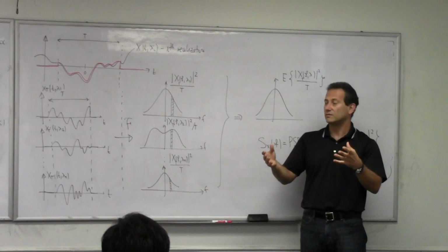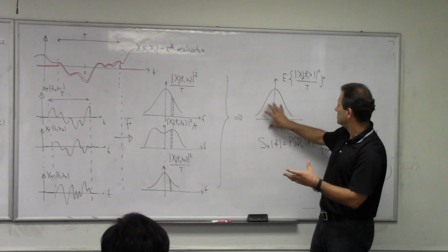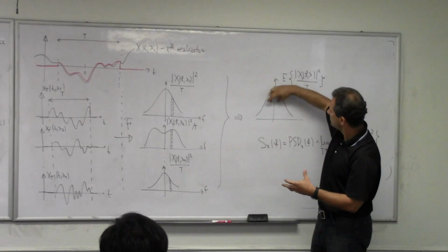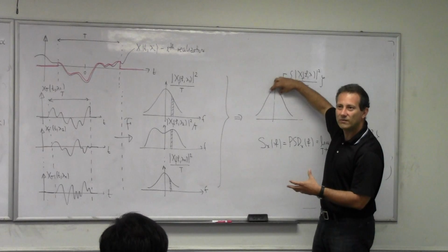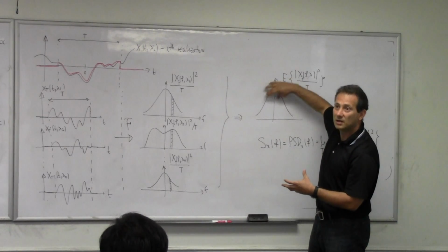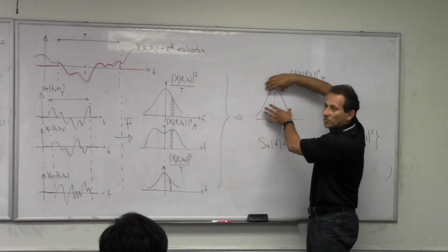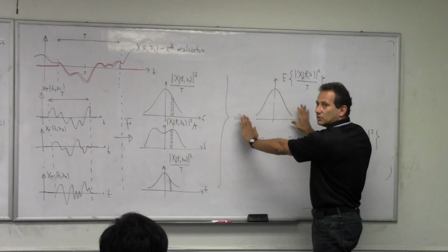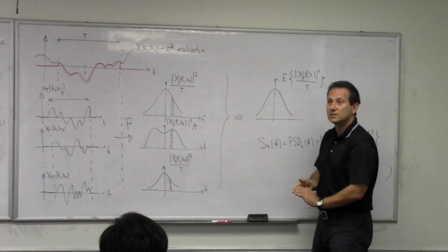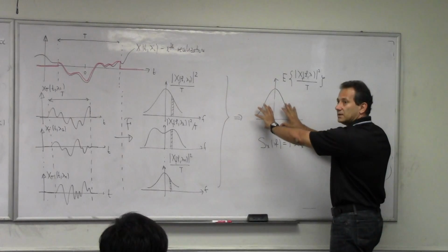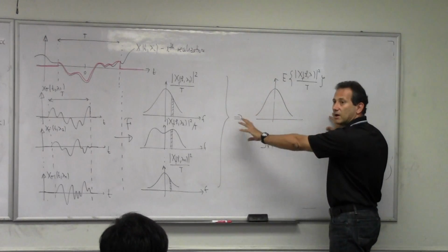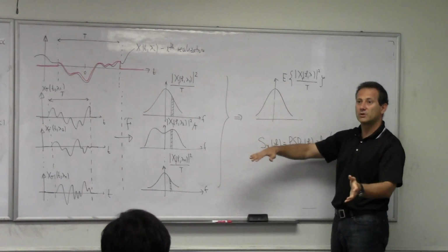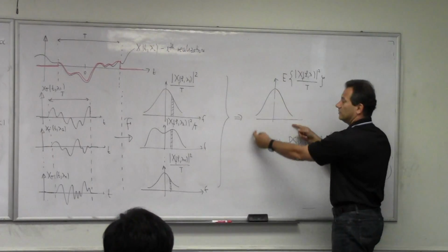And if I say the power spectral density of the process looks like this, let's just look at this as an example, not general, then you can say, oh, this process is predominantly around DC. It is slowly varying because it has a high dominance of these low frequency components. They participate more, right? Because this power spectral density is larger there. And then there is some variability on the top because the signal has these higher frequency components as well. But this variability becomes less and less powerful as you move away in the frequency domain. So this process is predominantly a slowly varying process that has some noise on the top of it as a result of these tails, right?